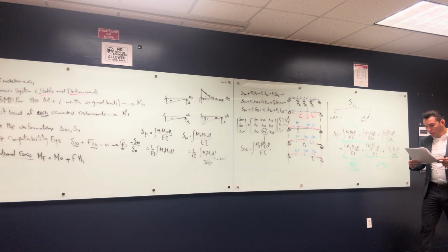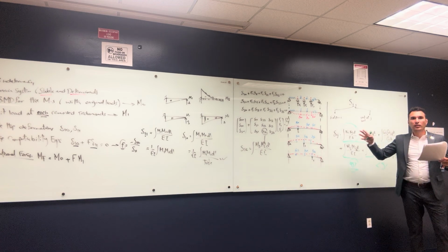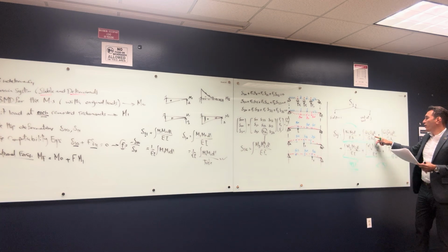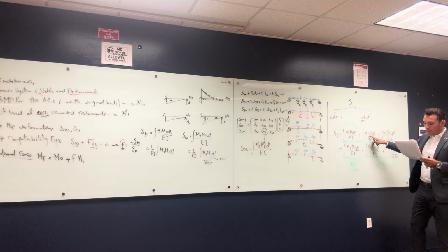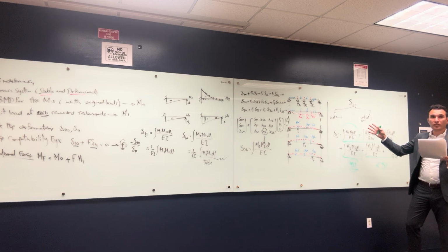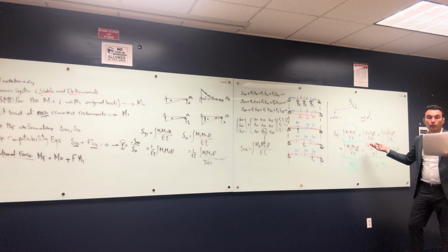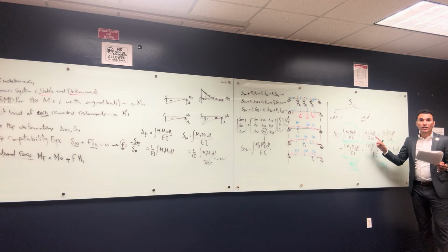AR, there is a table for it in the textbook. It's called a reduced area. AR is alpha multiplied by A. It's a reduced area for shear. And G is a function of the Young's modulus and the Poisson ratio, called the shear modulus. In the textbook, Fundamentals of Structural Analysis, the one in the syllabus, you can find how to calculate this.